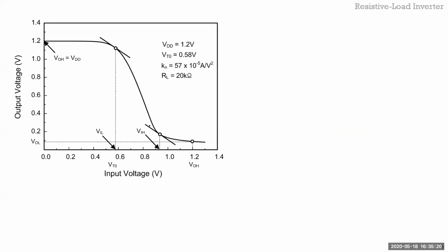All right, so we calculated VOH, which was VDD. We calculated VOL, just the resistor divider. We used the resistor divider principle to do it. VIH, so what I'm going to do is I'm going to show you a quick way, the principle behind how to calculate the other two factors, which is for the noise margin, I also need the VIL and VIH, right? So for the inverter, so let's calculate VIL.